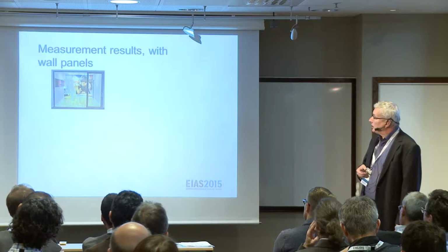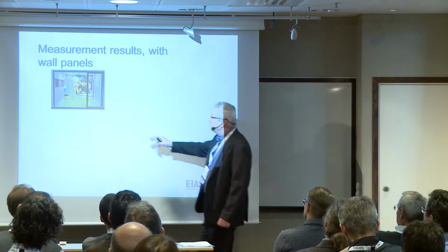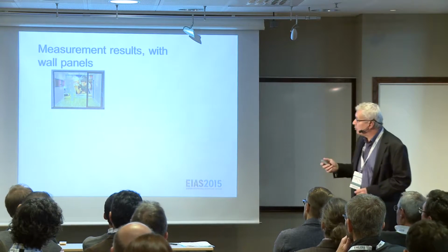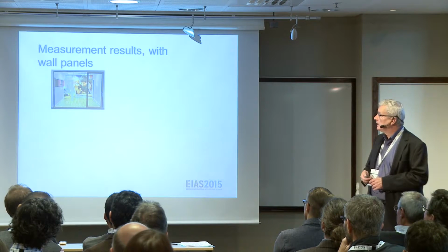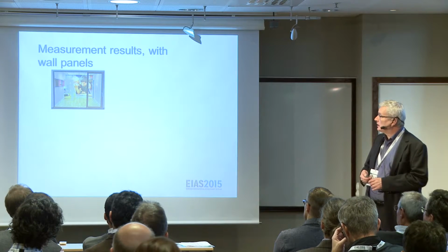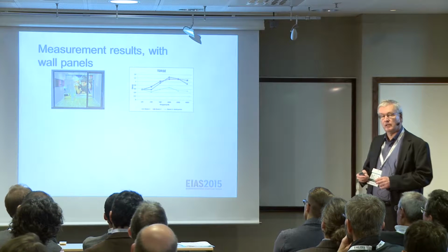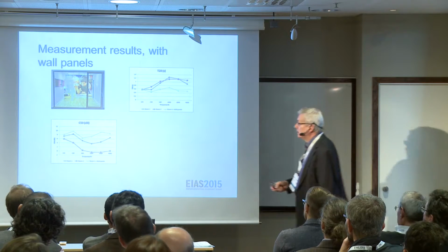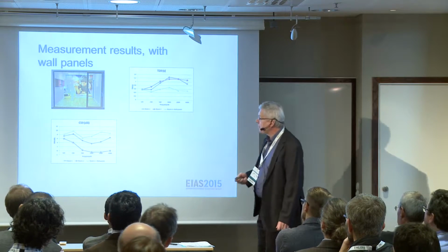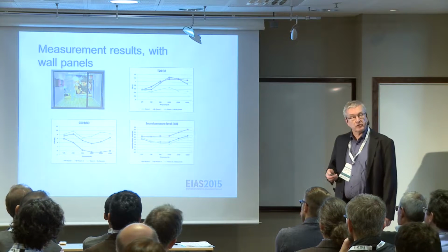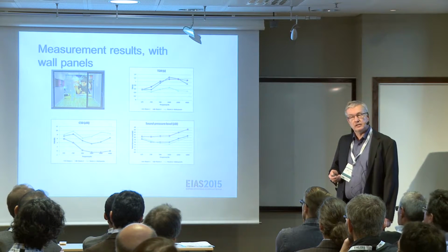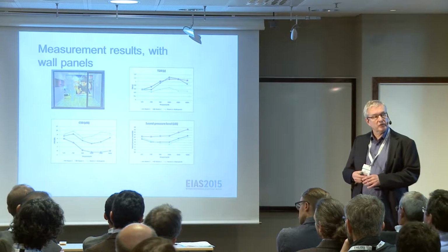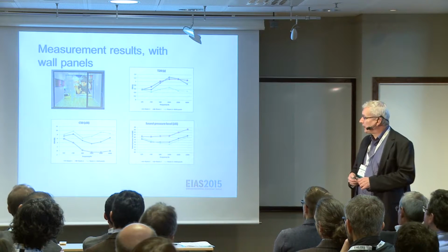We also did another small experiment where we put in some wall panels, just 4 patches of 600 by 600, into room number 1 with the highly absorptive ceiling. You see that only this small amount has quite a large effect on the reverberation time, and even on the speech clarity, but not that much on the sound pressure level. So you see that there is really a need for more parameters than reverberation time to explain all this behavior.